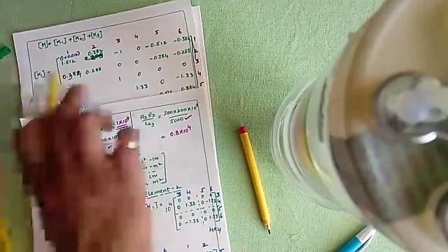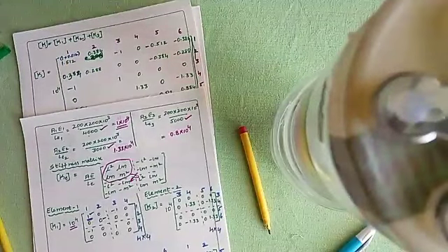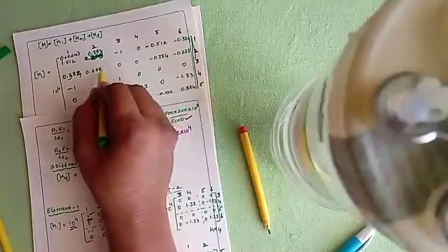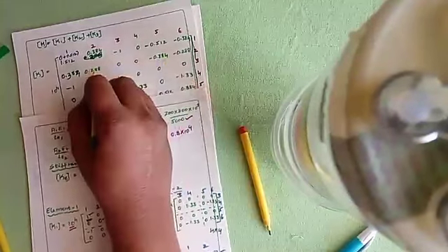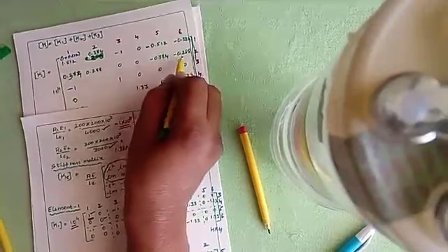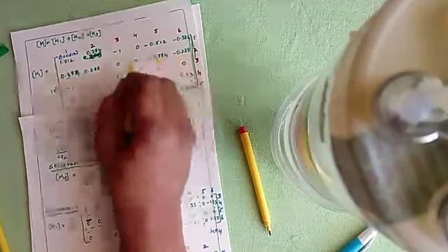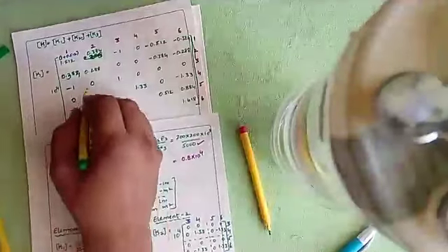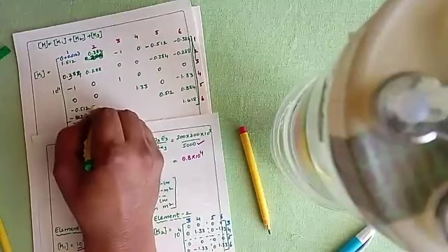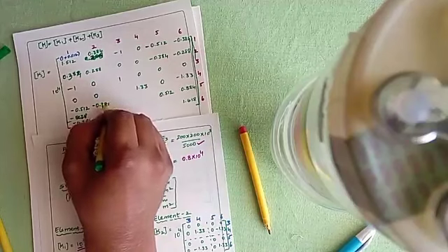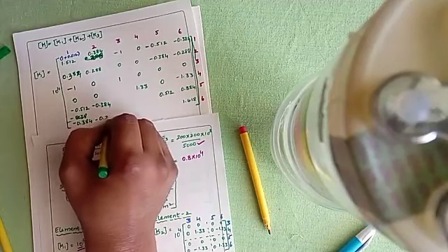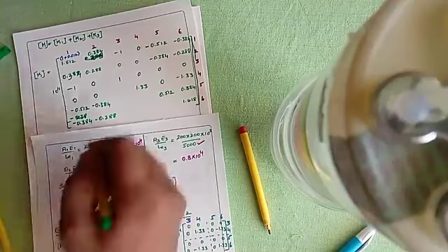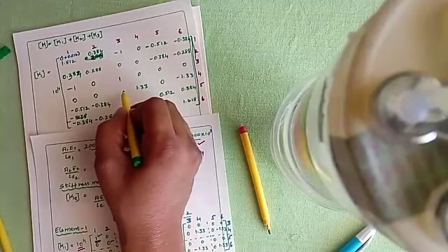0.288, 0. Like this, if you try to form a stiffness matrix by looking at the values. Now see, I've done the second row also. 0.288, minus 0.384, minus 0.288. Now the second row will be replaced by the second column. 0, 0, minus 0.384, minus 0.288. Like this, if you just try to look into the matrix carefully, you can form the global stiffness matrix.